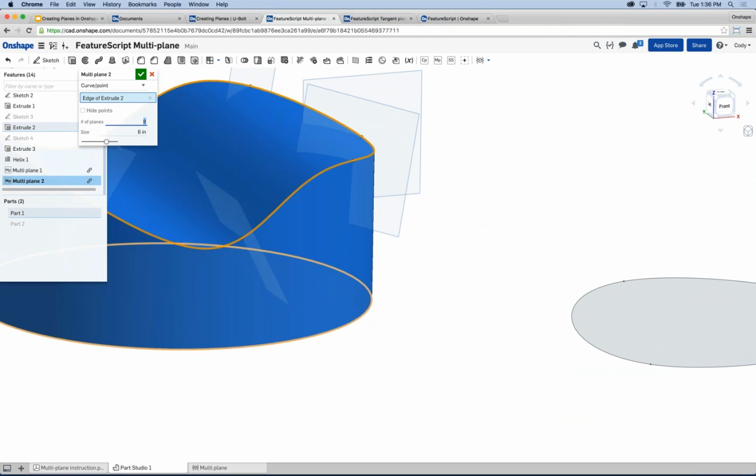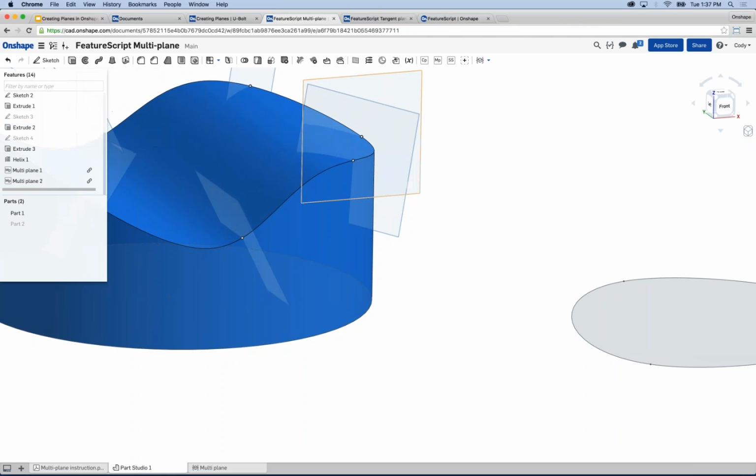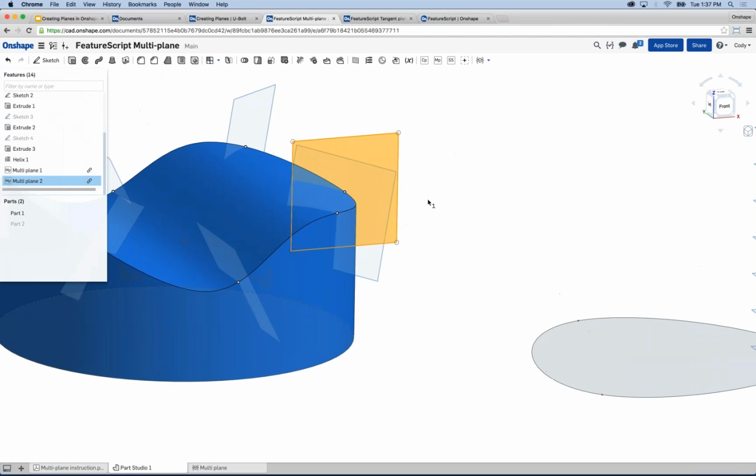Okay. All right. So a few questions that have come up. Can you still drag them to resize, or are they set the size in the feature? And this is a very good question. I mentioned before, all planes can be resized. If you left click a plane, you'll see these little arrows or these little circles in the corners where you can grab the arrow and drag it. And that will allow you to dynamically resize the plane. Okay, so if you're the type that likes to see the plane a certain size, you can grab and drag it and resize it to whatever size you'd like.